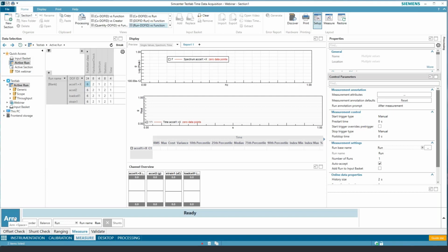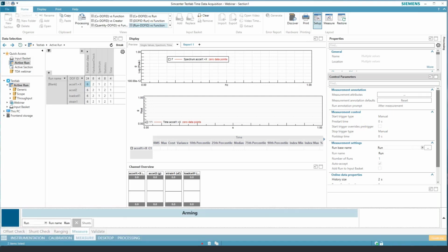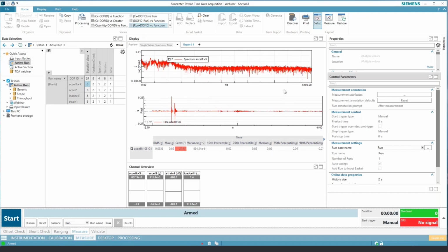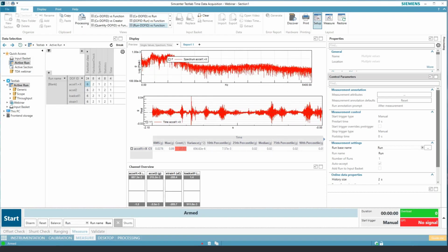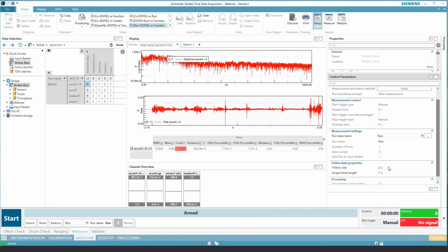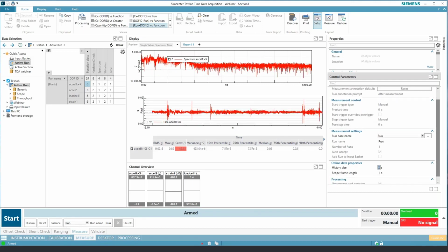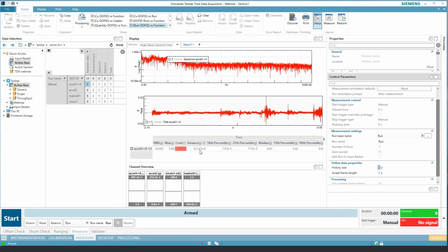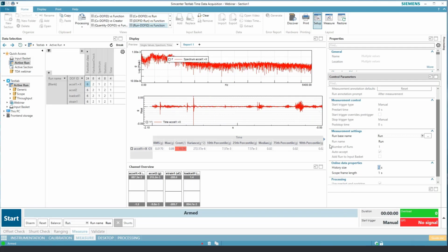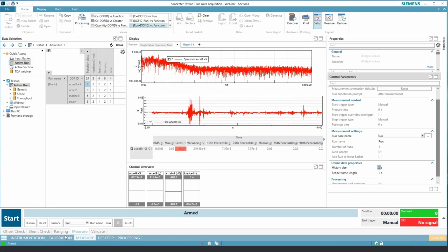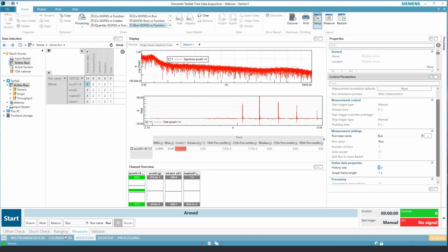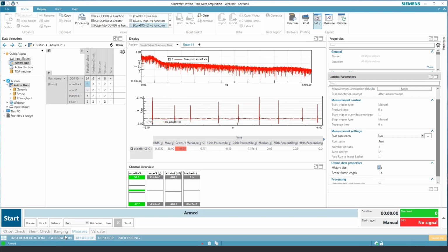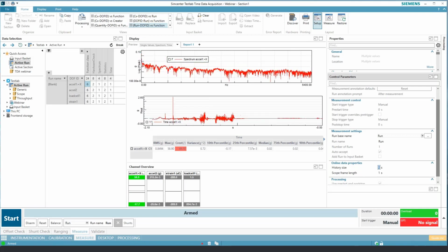And what I wanted to illustrate was when I arm the system now, data starts flowing into the displays. By default, I've got a time history display here of 2 seconds. I can change that down here in the properties, bump up that time if I want more time displayed, as well as some statistic and hardware information and the channel levels. Tap away on the Excel here, you can see my impacts on the tabletop as well as the level I'm achieving in the channel overview.